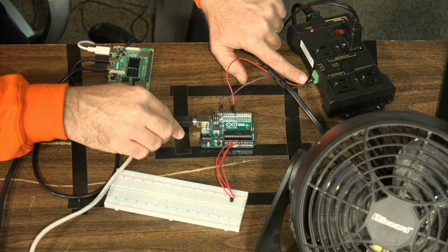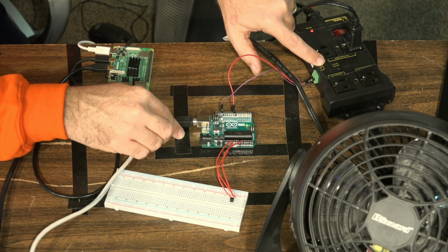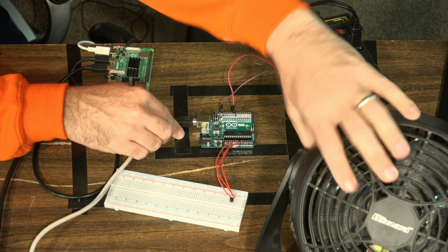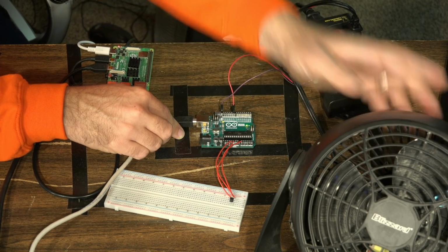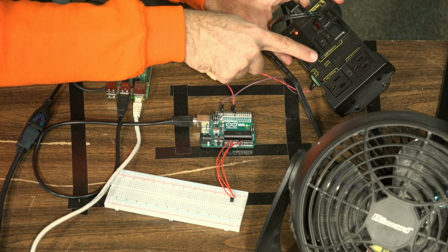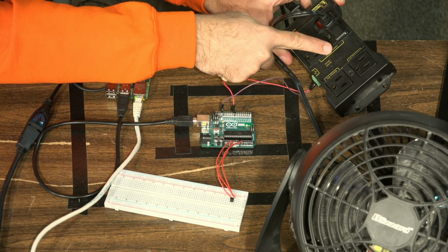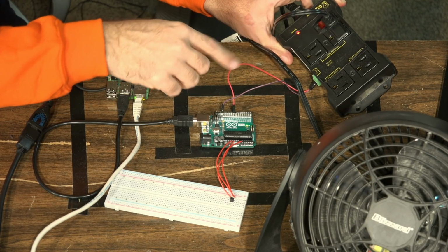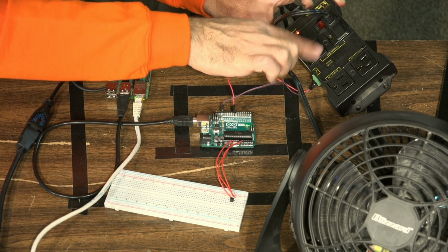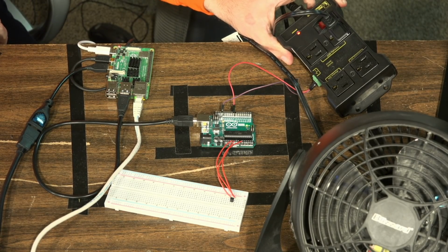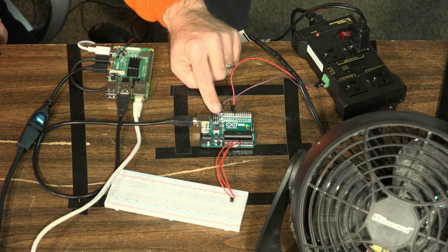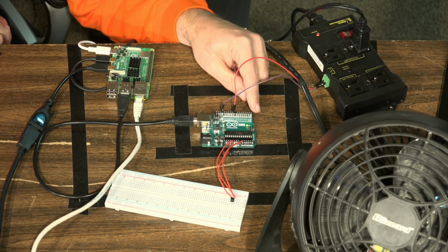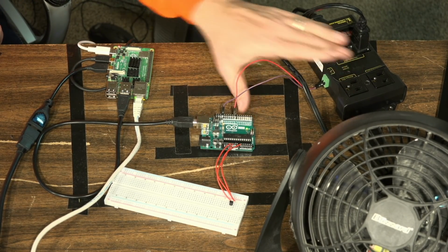The addition that it has for you is the little on-off switch that you can connect to your Arduino on the side. So I have my fan here. My fan, the power position on the back is set to on. And then I have this plugged into the relay for normally off. So normally the fan will be off, but then when I get the signal to turn the fan on or turn the power outlet on, it will turn the power outlet on. From there, basically ground simply goes to ground on this side of the Arduino, and then for the digital pin, we are going to digital pin 8, and that is the basic setup